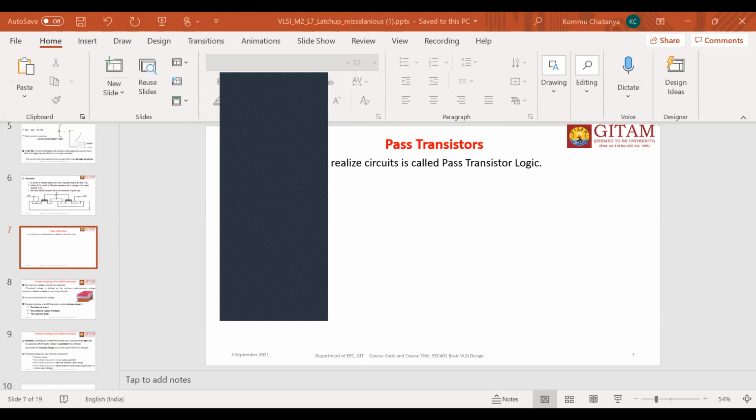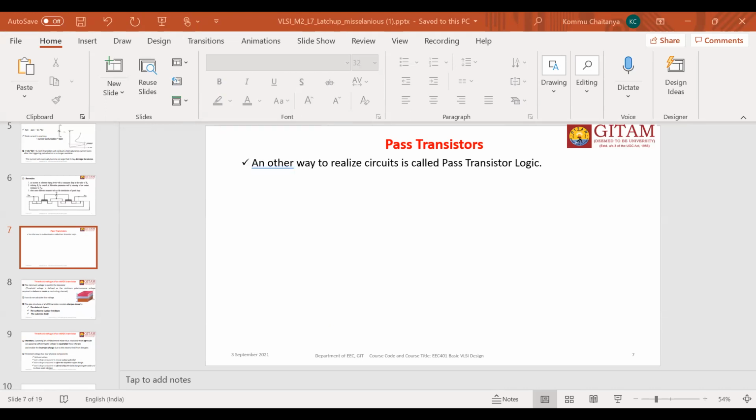This is n plus, of course. So for example, this is n plus, this is also n plus. This is a p substrate. Okay, what does it resemble? It is simply a diode, right? It is simply a diode. So the diode is formed. In order to characterize this particular MOS transistor in a circuit, in order to model this transistor, these things will be taken into consideration.